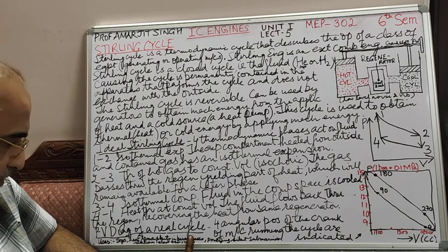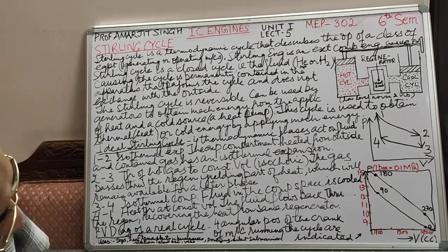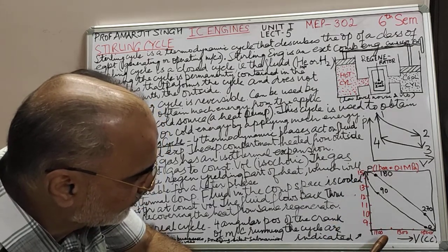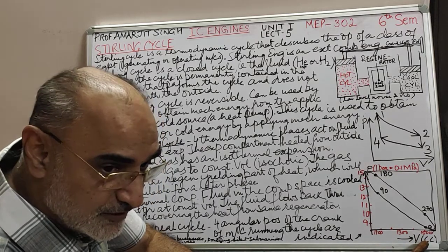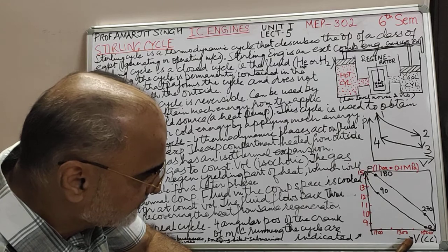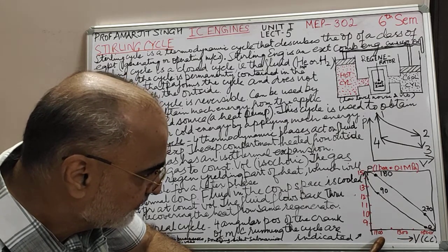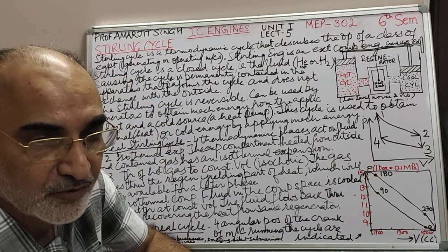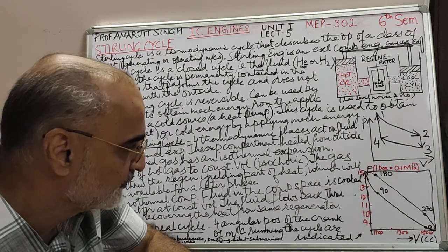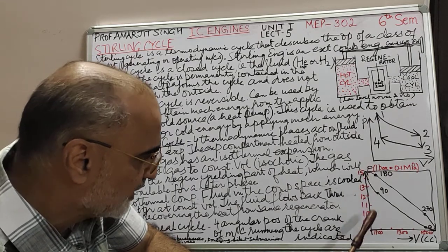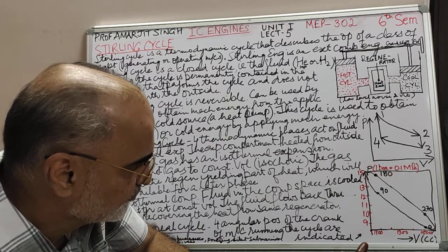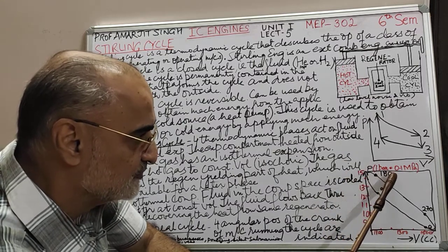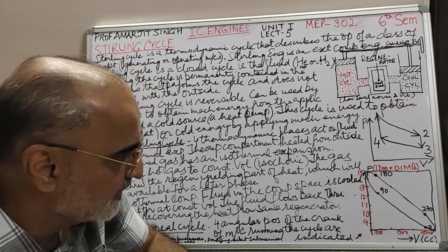Now let us look at the PV diagram of a real cycle. On this PV diagram, the volume of the engine space, or the contraption, is shown as 1100, 1200, 1300, 1400, 1500, 1600 cc. We have got a 1600 cc contraption. The pressure is shown in bars on the pressure scale: 9, 10, 11, 12, 13, 14, 15. One bar, as you know, is 0.1 MPa.